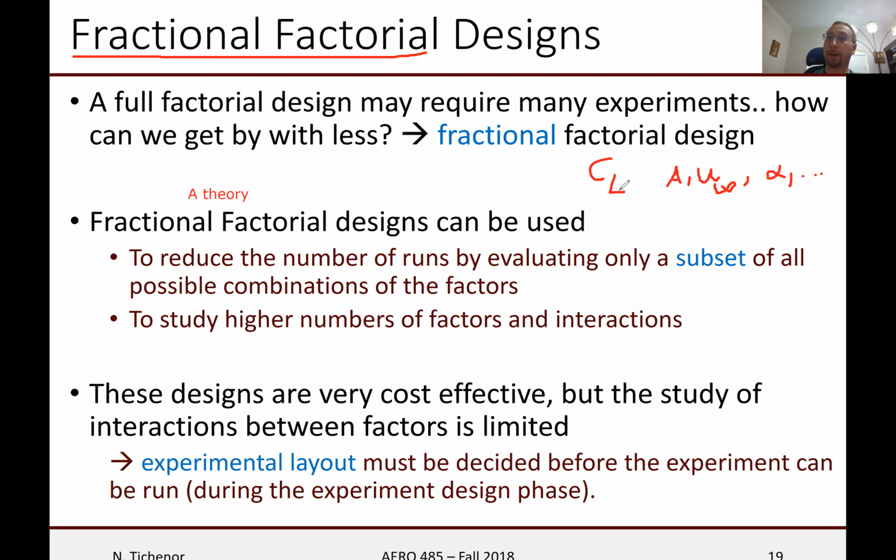We came up by doing a non-dimensionalized approach, which I hope you remember from 201. We related the lift to CL, dynamic pressure, the 1/2 rho u squared, and angle of attack, and the CL hat angle of attack and cross-section area.